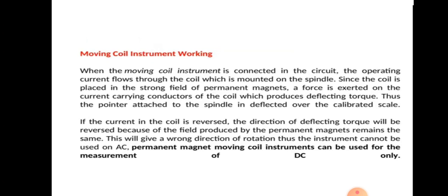Second point is, if the current in the coil is reversed, the direction of deflecting torque will be reversed because the field produced by the permanent magnets remains the same.